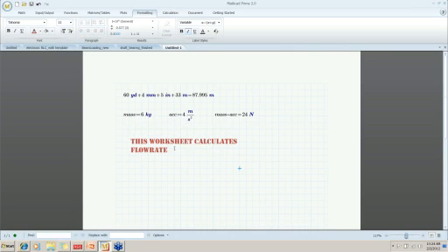Now, one thing that I want to mention is that all of the keyboard shortcuts that we expect and try to use that we couldn't use in Mathcad before now work in Mathcad Prime. So if we want to underline, it's a minor thing, but we can highlight it, and then just use Control-U on our keyboard, and it'll underline it. So that's, again, going back to the usability. We couldn't do it before. It's a minor thing, but it really makes it easier, so you don't have to keep going up to the top and clicking on the U or the B to bold or underline. Those keyboard shortcuts that work in Microsoft Office applications like Word, Excel, PowerPoint now also work in Mathcad Prime.